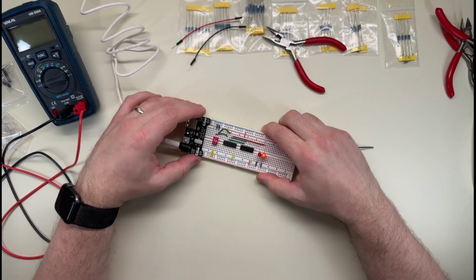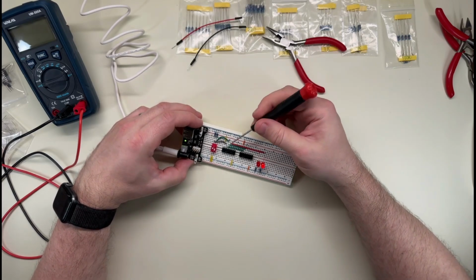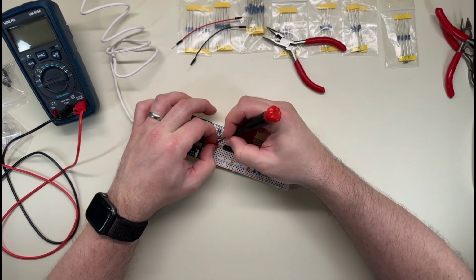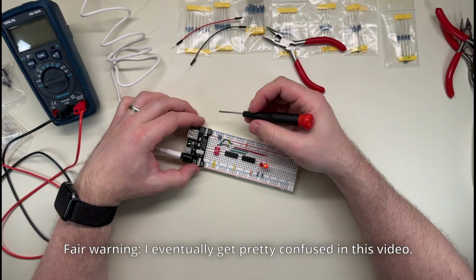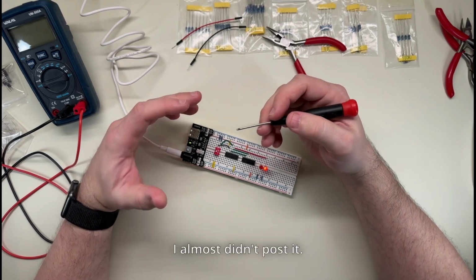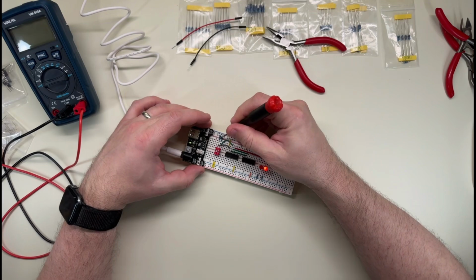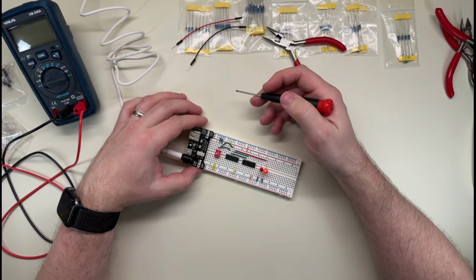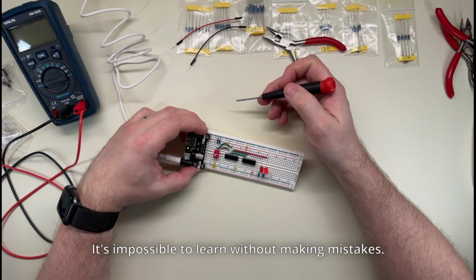Previously, I made this 1-bit adder with my son, and we went through how the logic works to add two 1-bit numbers together in binary. One thing we did was use these pull-down resistors, which you need to keep the values from floating, right? I'm still never quite clear on what values I should pick for these resistors, and I'm curious as to why. So I thought maybe I'll make a little video where I poke around and we see what happens. These ones in here are 1K resistors, and I picked those arbitrarily.